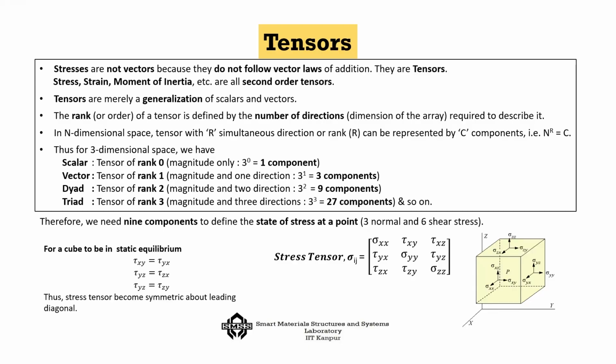As you can see in this particular case here, there are such stresses, for example, sigma yy or sigma zz or sigma xx. So, these 3 axial stresses are directly possible. Similarly, there are these shear stresses sigma xy, sigma yz and sigma xz or sigma zx.